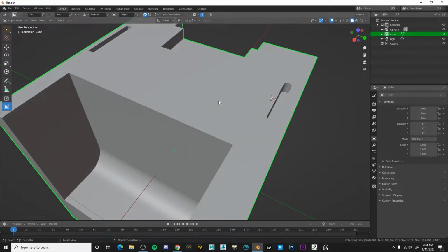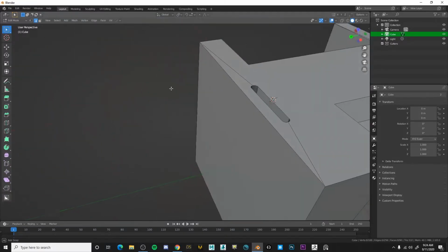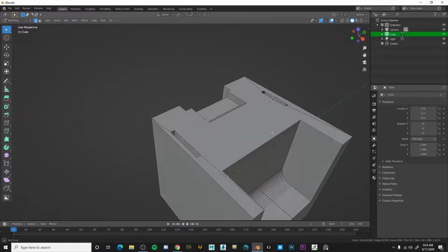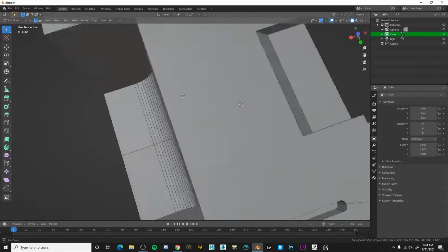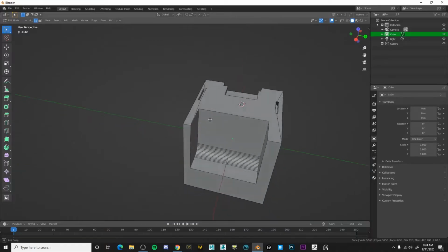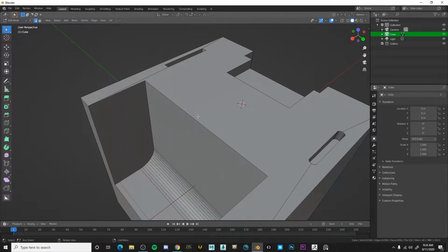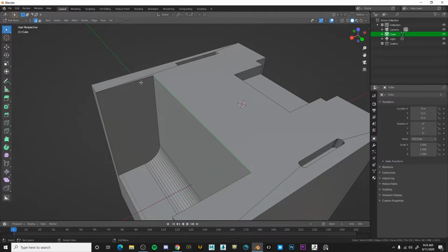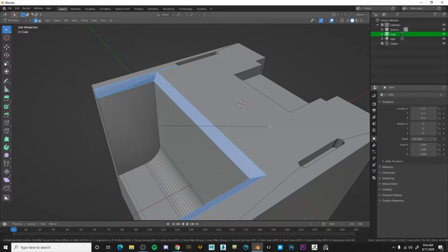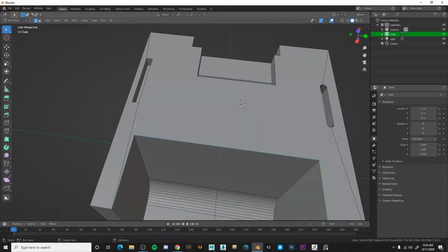So yeah, let's go to the edit mode and see how it looks. As you can see, now it's a mesh itself, and it looks really well. So this is one really cool thing about Boxcutter, and now I can just do whatever I want. I wanna select these, just Shift select. I want to add booleans to it, then do it. Okay, so this over here is interfering, so I'm just gonna leave it.